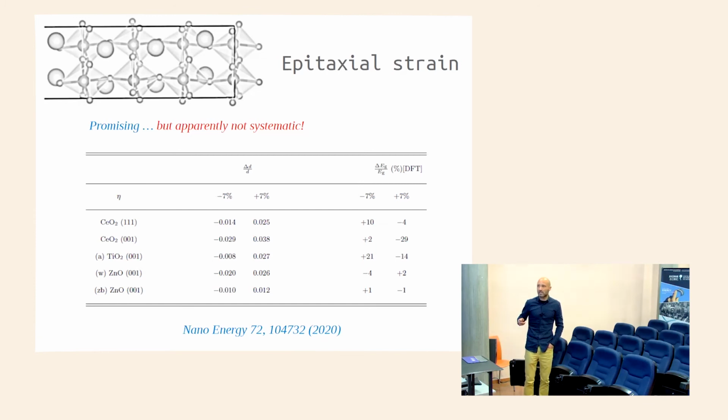So for instance, we have here the same material and the same tensile stress, with a very similar deformation with respect to the unstrained case. However, the effect on the energy bandgap is much larger here. It's a factor of almost 7, from the same material, when you apply the stress in one surface or in another, right?